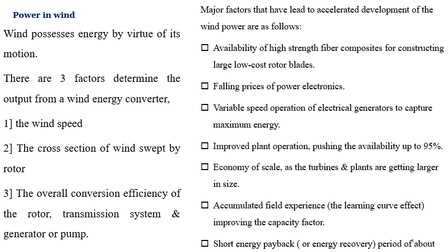So all these are very important factors which accelerated the development of wind energy. We know there is no device, however well designed, that can extract all of the wind's energy, because the wind would be brought to a halt, and this would prevent the passage of more air through the rotor. The most that is possible is for the rotor to decelerate the whole horizontal column of intercepted air to about 1/3 of its free velocity.